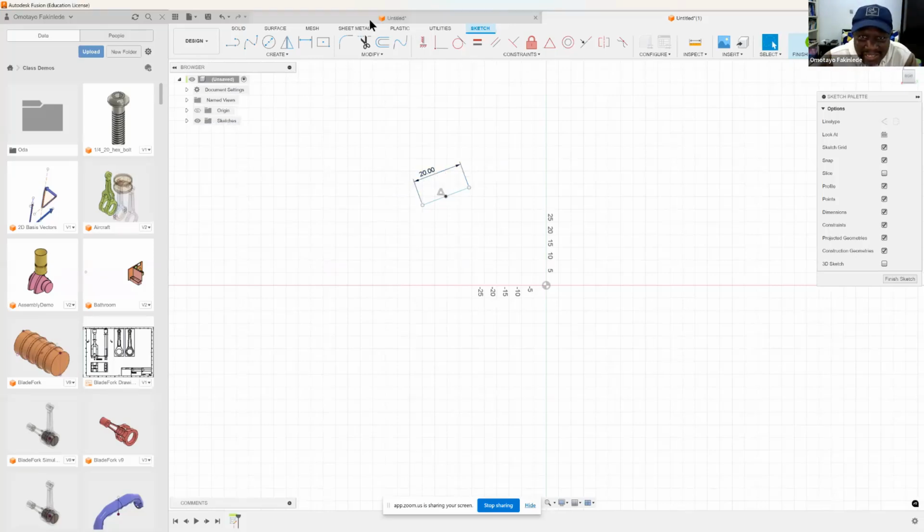So the next thing I want to do is to make the center of the line coincident with the origin. So I'll choose the coincident constraint. I want this center and the origin to coincide. So you can see I brought the line to this, and the center is at the origin. The next thing I want to do is to further constrain it to be horizontal. So I constrain it to be horizontal, and that is it. So that is how I want you to draw the line.